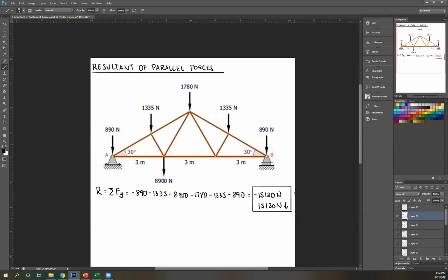Next, second part. Now, if you stare at your thin truss, you can see that we'll encounter a problem. If I extend this force, its perpendicular distance from either side would be a certain distance, right? And it's not given. The only thing that's given is this. So first part is I need to solve for that. Let's put that there. And then this is x. So we're solving for x. To solve for x, you're given this 30 degrees here. And then this is a thin truss, meaning this is perpendicular to this.